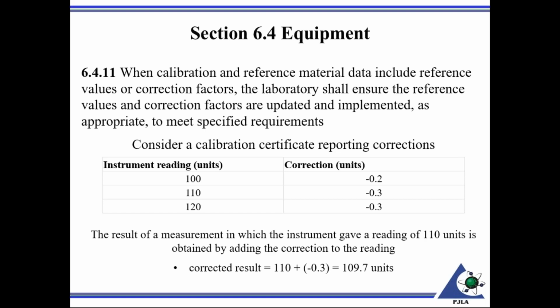So if you need to incorporate those correction factors into your testing or calibration, then that would be carried forward into the testing and calibration protocol. When you use that device, you also take into account, if it's applicable, the correction factor. Often if the device is within tolerance and it's determined, hey, it's not going to affect anything, just as long as it's within that tolerance, it may not be necessary to carry the correction factors forward.